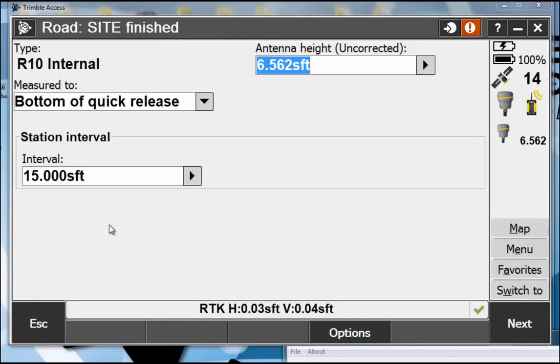All right, so that would be the back of curb alignment. So we've got kind of pros and cons with DXF, which we've seen here. The difference between staking that back of curb RXL in general survey versus roads. The last thing that Brian looked at in there was the pipe runs, right, the structures. So two things he exported. We had the CSV file that had all the center of structure locations, okay? And then we had the actual pipe run alignment that had all the inverts defined as well.